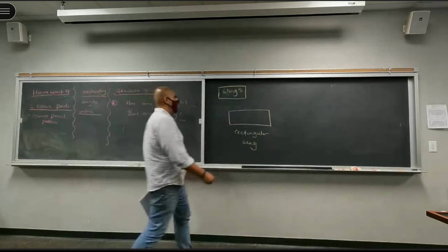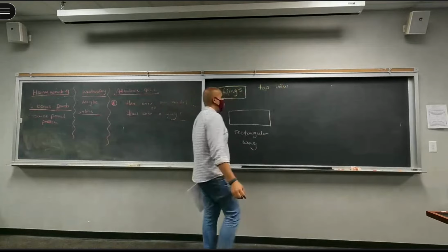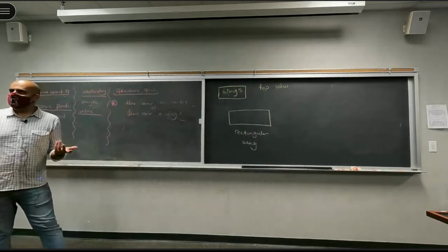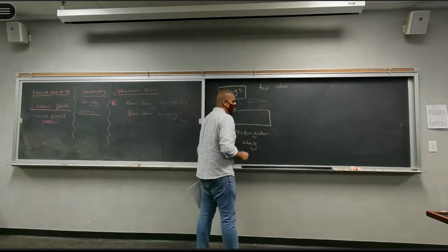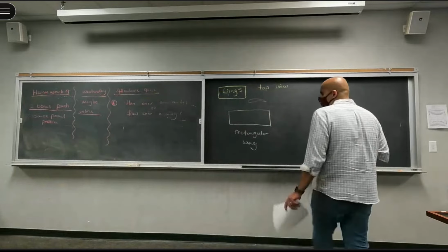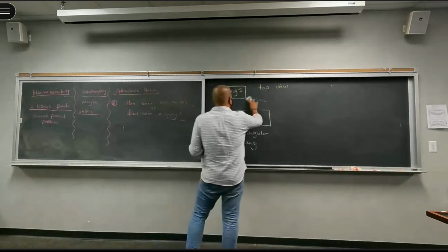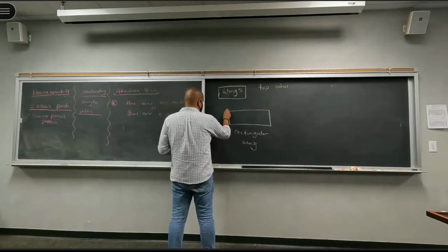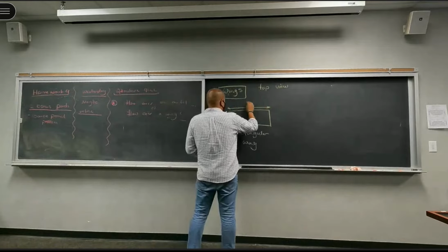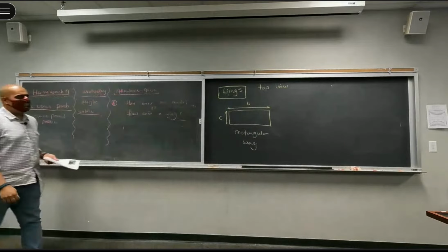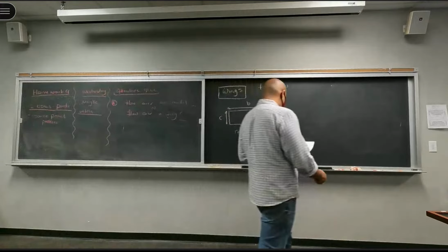And this is a top view. All of the views you're going to see here are going to be the top view of the wing. If you look at this wing from the top, you will see a rectangle. From the side, it will probably look like an airfoil, right? But from the top, it will only be a rectangle with a chord length that is constant throughout the wing, and a span, a wing span. Okay, that's the most fundamental type of wing that you may use in aerodynamics or aerodynamic design.